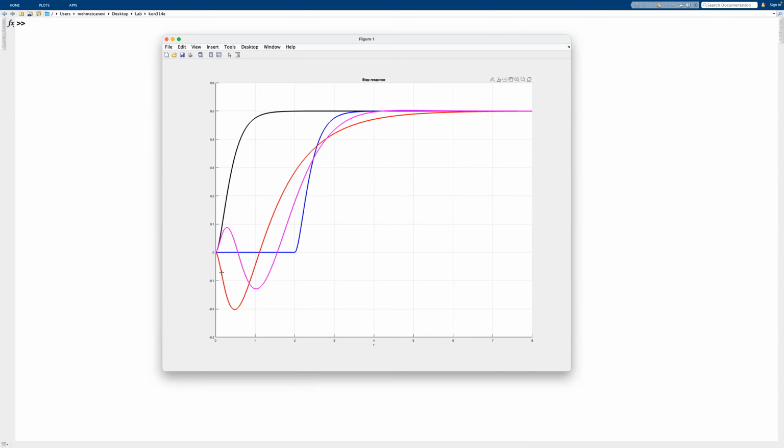So it has undershoot, it goes like this, and it returns to the point where it started, basically 0. So therefore we have a 0 crossing at this exact point, which is approximately 1.1 seconds here. So I could assume that the red one here has 1.1 seconds of delay or dead time because we started from 0, wasted some time, and returned to 0. And now we're starting to react in the right direction.